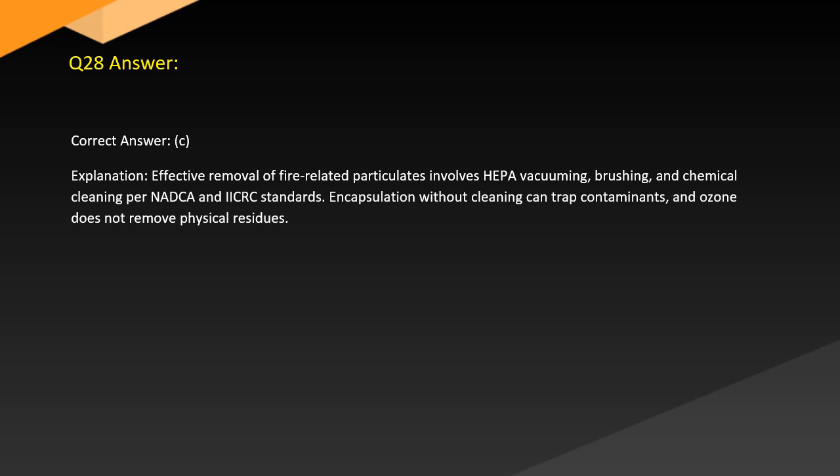Answer. Correct answer. C. Explanation. Effective removal of fire-related particulates involves HEPA vacuuming, brushing, and chemical cleaning per NADCA and ICAC standards. Encapsulation without cleaning can trap contaminants, and ozone does not remove physical residues.